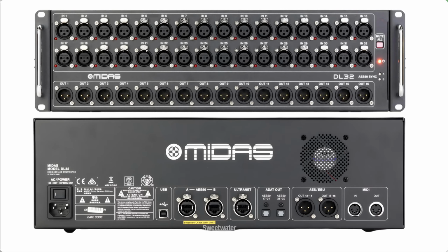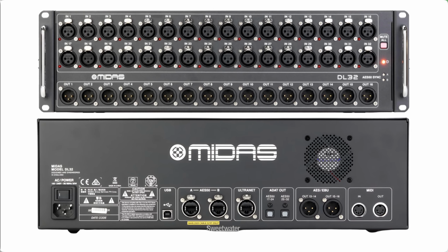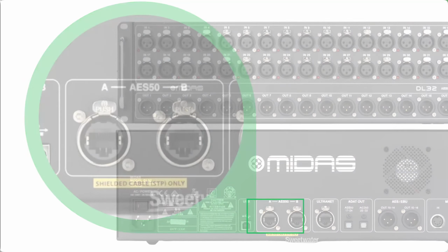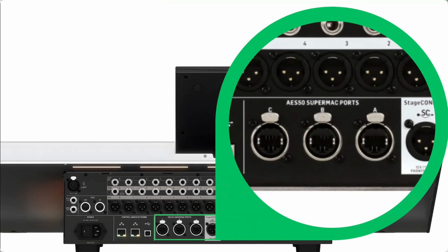Going back to some cleaned up images, you can see here a front and rear view of the stage box. Down here towards the bottom is the Ethernet port connection that makes connecting to the soundboard possible. This is called an AES50 port, and it allows for two-way communication between any other device that has an AES50 port. And surprise, we have 3 AES50 ports on the back of our Wing soundboard. So now the soundboard can talk with the digital stage box over only one Ethernet cable.